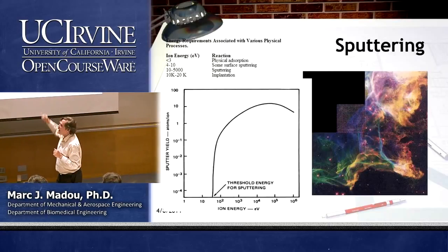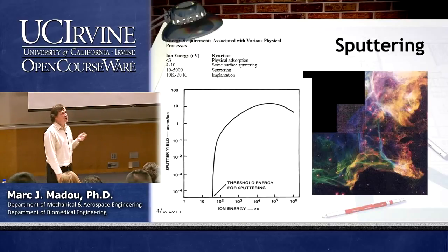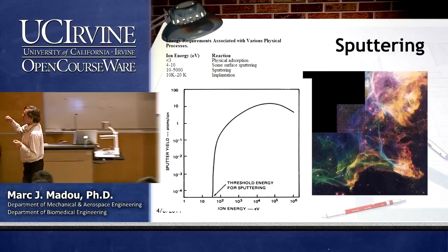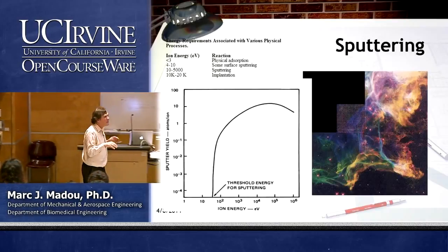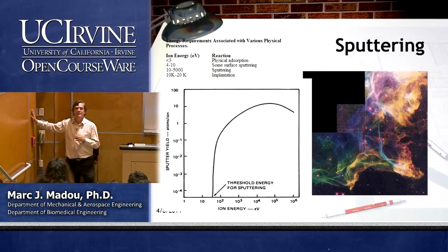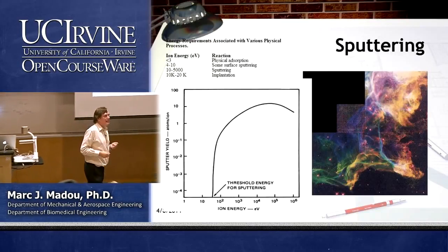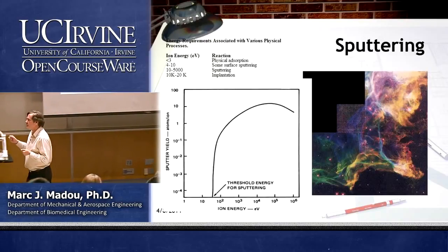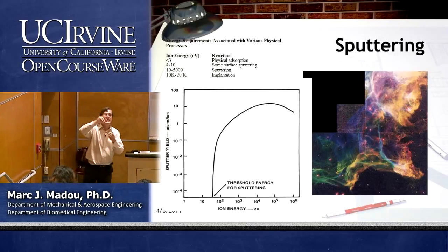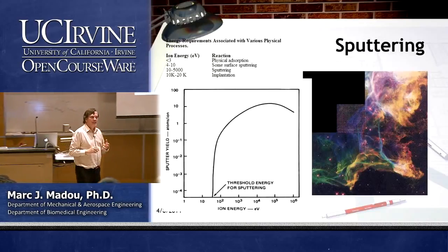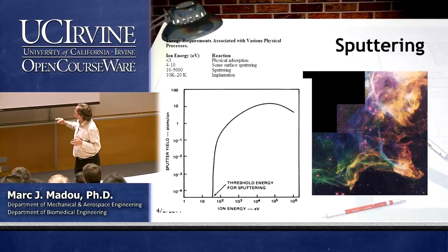What it says is that an ion, let's say it's argon plus, has an energy of less than 3 electron volts, and it's going to hit this wall. What will it do with 3 electron volts or less? All it will do is maybe stick there. That's it. Now I'm giving it a bit more energy, 4 to 10 electron volts. You know what it might do? There's some dirt on there, some oil, some carbon, some oxygen. It might displace it. It starts sputter cleaning a little bit. This is already a manufacturing technique: sputter cleaning with ions when you have an energy of about 10 eV.